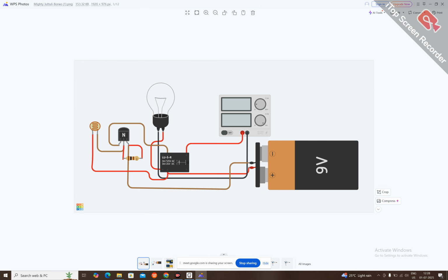Yeah, so this is the project. If you observe in this project, we have a few discrete components and a few power supply related components, and we're directly using the 230 volts power supply. Okay, and we are using a DC source, but generally we will not have a DC source directly from the 230 supply. We are supposed to create our own DC source. That means we have to get a DC from the AC.